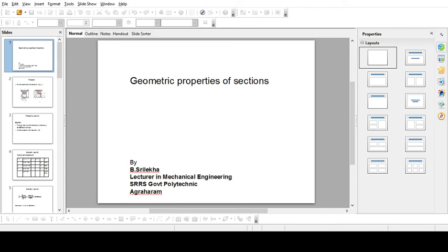Now the area of the trapezium is h by 2 into (a plus b), which is 120 into 500 by 2, so that will give you 30,000. Next, the y term is 56, so ay is 16,80,000.